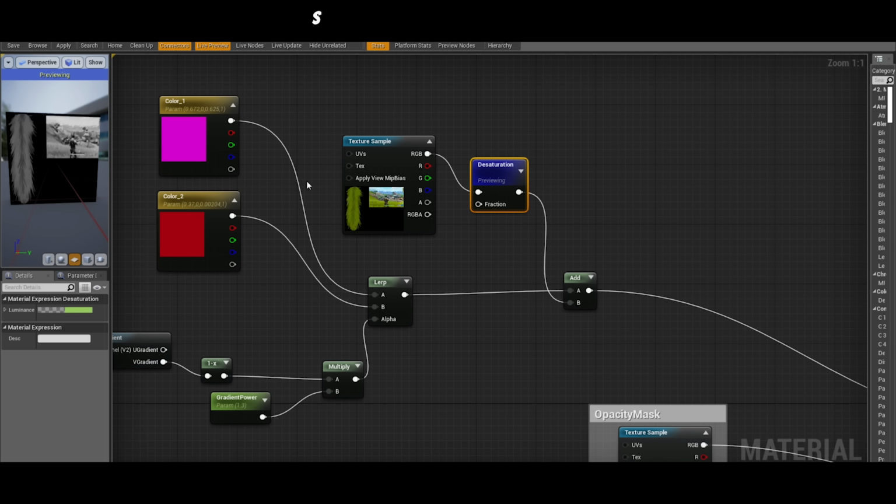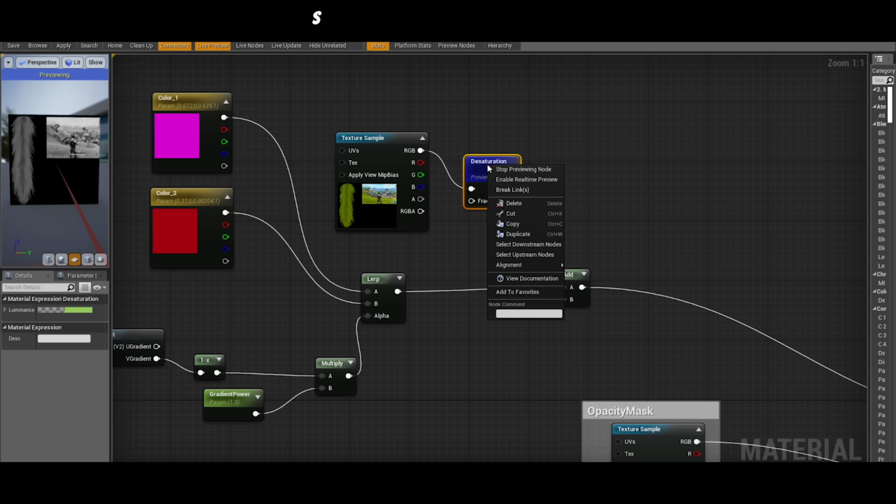So if you wanted to optimize your texel density for this kind of albedo map, you should probably have the painting on the diagonal over here so that you cover more UV space. But it's fine like this. But if you're doing this, I would recommend you to do it on the diagonal so you get more UV space and more resolution texel density.